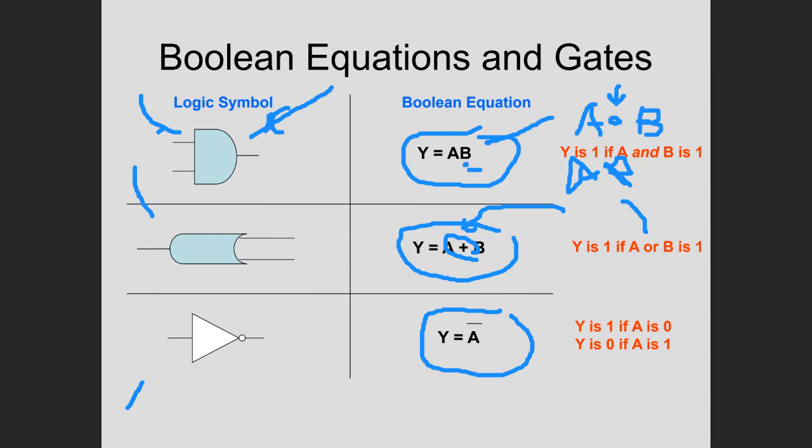We can think of it the same way when you're ANDing. Strictly speaking, when you're ANDing, we're going to use this symbol right here, the dot, but you can just write it like you would write a product of variables, and it's understood to mean ANDing. We'll do that throughout the course where we won't write the dot operator. You could, it just takes an extra step. But anytime you see a multiplication in logic, in Boolean algebra, what you're doing is ANDing.